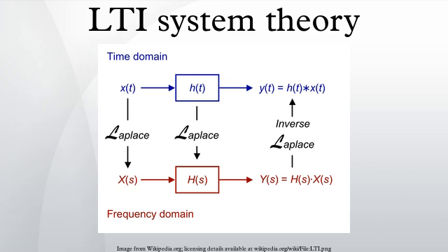Because sinusoids are a sum of complex exponentials with complex conjugate frequencies, if the input to the system is a sinusoid, then the output to the system will also be a sinusoid, perhaps with a different amplitude and a different phase, but always with the same frequency upon reaching steady state. LTI systems cannot produce frequency components that are not in the input.